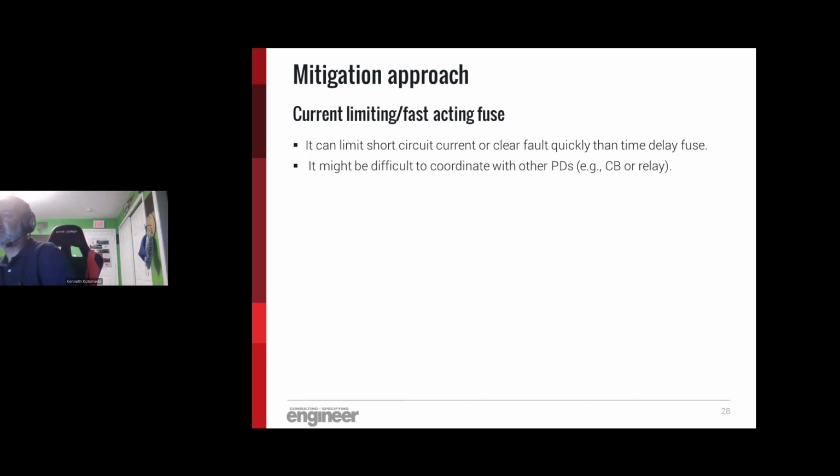I think the first step is to look at your arc flash study, see what you can do, and adjust the ratings. I did a lot of studies with mission critical facilities where they tend to set everything as high as it can so that you don't have any trips. And when you went in there, that really affected the arc flash. So you had to really go through and try to adjust those settings. So that is a very good approach.